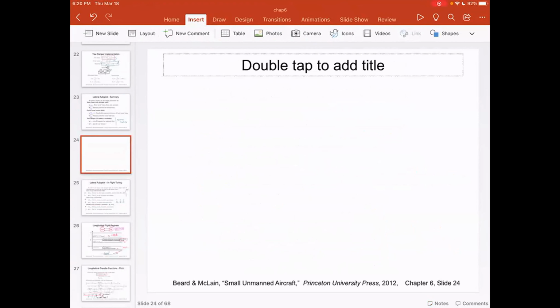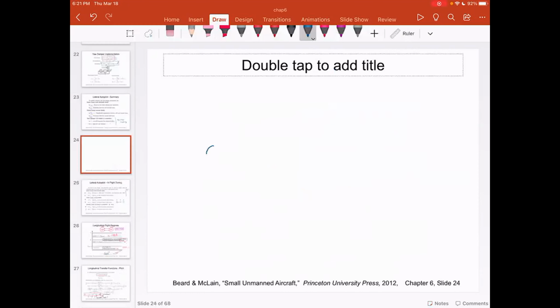So what does this side slip loop look like? If you look at the side slip loop, you have a summing junction, then you have a proportional gain, then you have an integral gain, then you have an integrator, then this integrator gets added at the summing junction, and then there is one more summing junction.